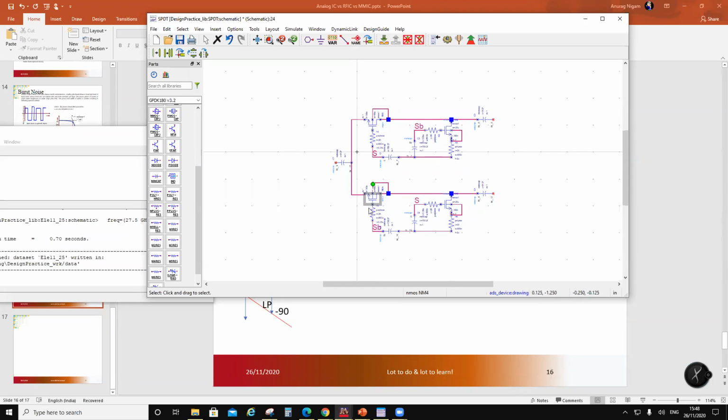Okay, so in the switch design, basically we have to worry about insertion loss in the on path, isolation in the off path, and the power capability of the switch. And all these are contradicting requirements. So the real design is, you can always put another series element over here, another series element. Now, people will try more crazy stuff. They will take this capacitance and anti-resonate it with another inductor. So they will put an inductor across this pass element.